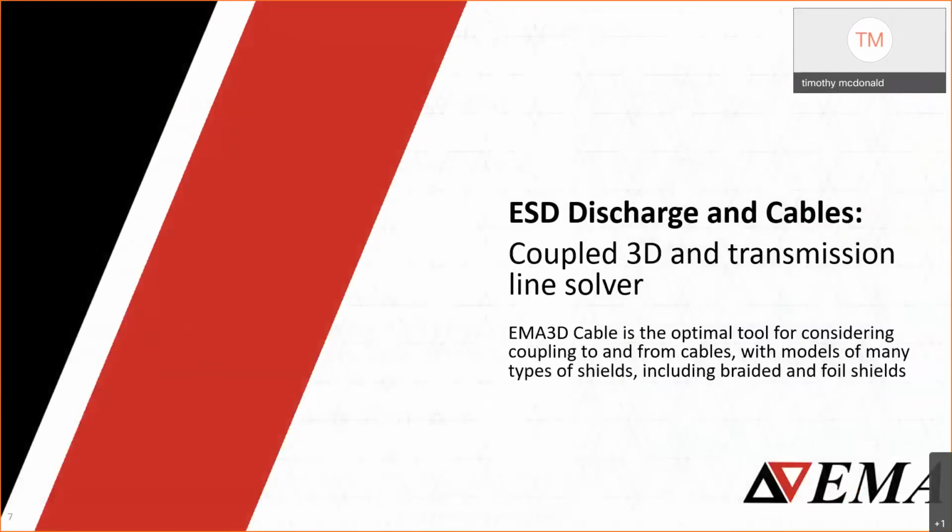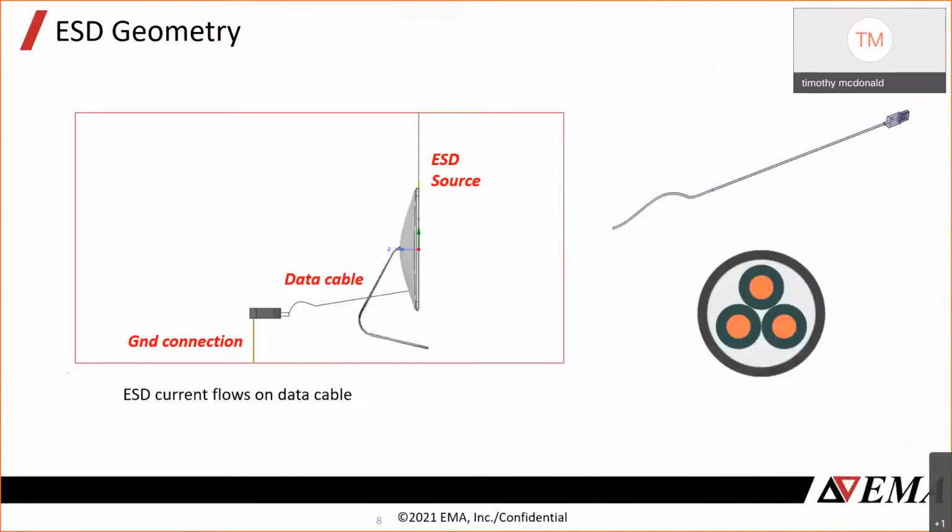Okay, I'm going to go through several concrete examples today. The first one we're going to look at is electrostatic discharge in cables. So with consumer devices or non-consumer electronic devices, there's many ways we can have a discharge. One of the biggest threats is just human ESD, where I'm charged up and I touch a touch screen on my car dashboard and I get a little shock. That ESD is something that is maybe considered safety critical, maybe really important to pass your EMI/EMC.